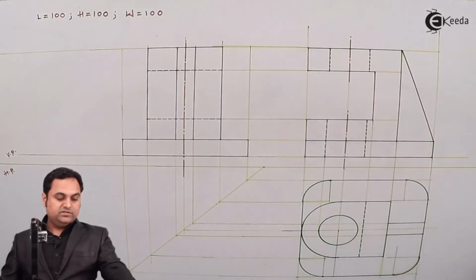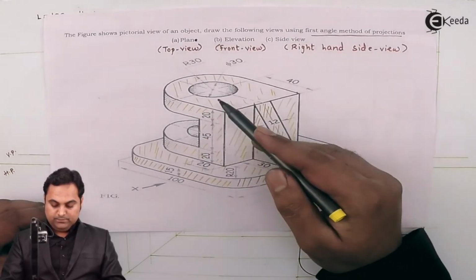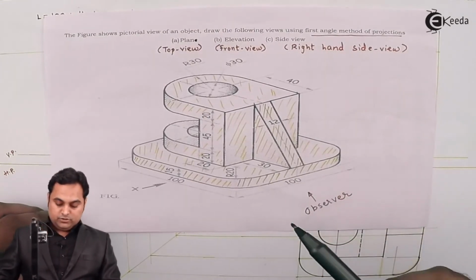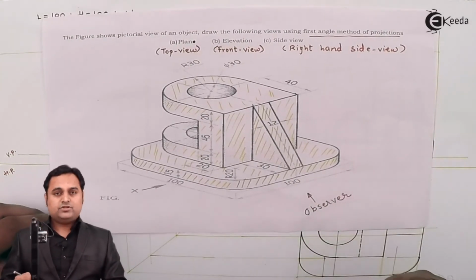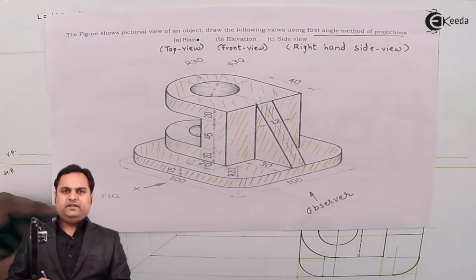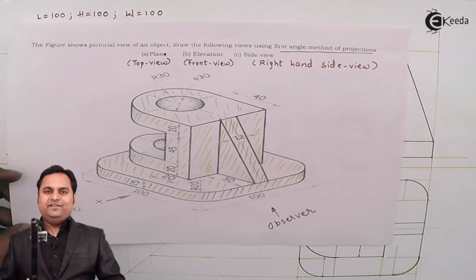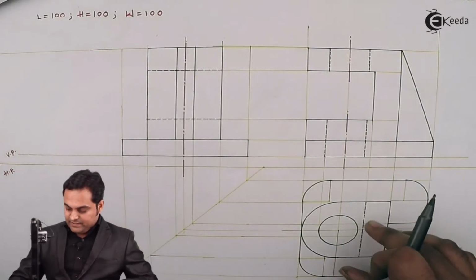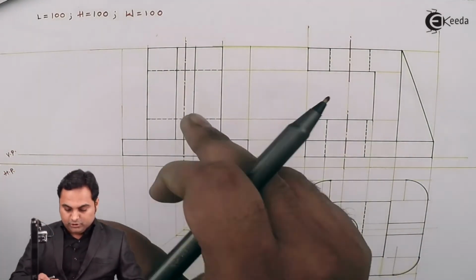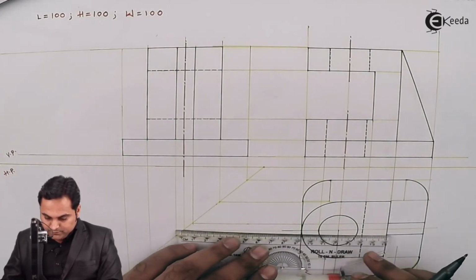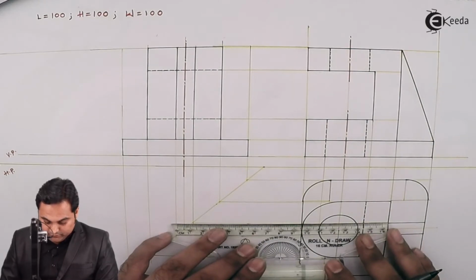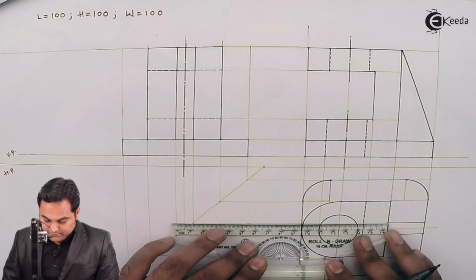There are two circles inside both the plates. They are also not visible from the side. So when we are drawing those circles, they will appear as rectangles with dotted lines. They are hidden. In order to project them, I can take the projection from the top view, because the height of those circles is already there. I need to know the width, which corresponds to their diameters.